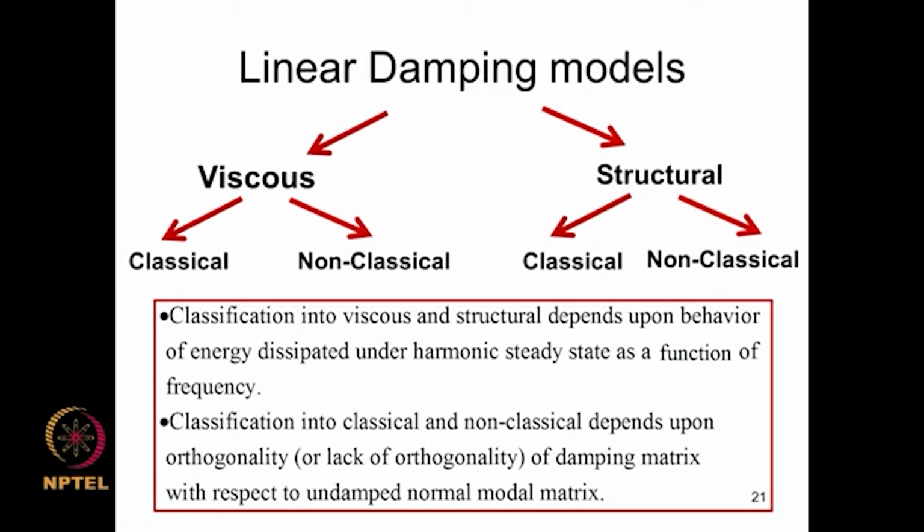Now, in trying to solve the governing equations of motion, we started by looking for certain coordinates in which the degrees of freedom become uncoupled, and we found that there are transformations from a given coordinate system to certain natural coordinate systems in which the degrees of freedom become uncoupled. The consequence of that is a coupled set of ordinary differential equations are solved as a set of uncoupled either second order differential equation or first order differential equation, depending on how we represent the equation of motion.